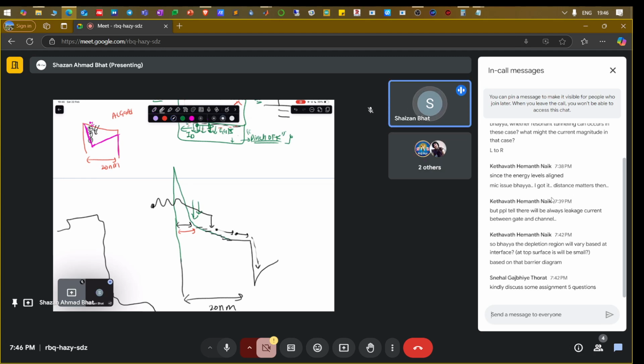Exactly. So what happened here now is that this particular part stays the same, but up to this particular value where you have, let's say, delta doping or some high doping, this is reduced to maybe 1 to 5 nanometers, and it's appreciable for tunneling to happen now, and then tunneling can happen. Okay, so this is absolutely possible. Got the point? Yeah, I got it.